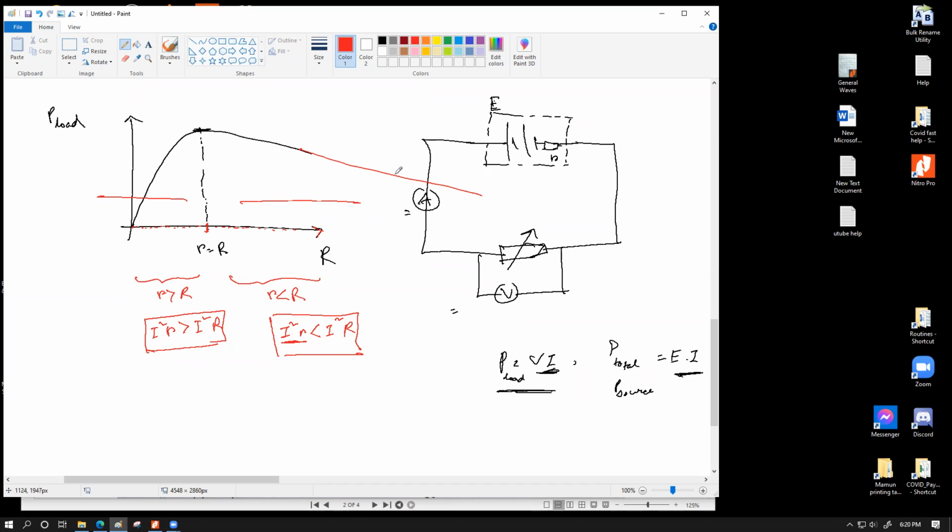We want to achieve a sweet spot somewhere on this decreasing graph, such that our output power or the load power is also quite high, so that it is useful for us. And also our efficiency is good, our wasted energy is quite small, so that we don't lose too much heat. Because losing too much heat is obviously a problem. You are going to run out of the battery pretty fast.